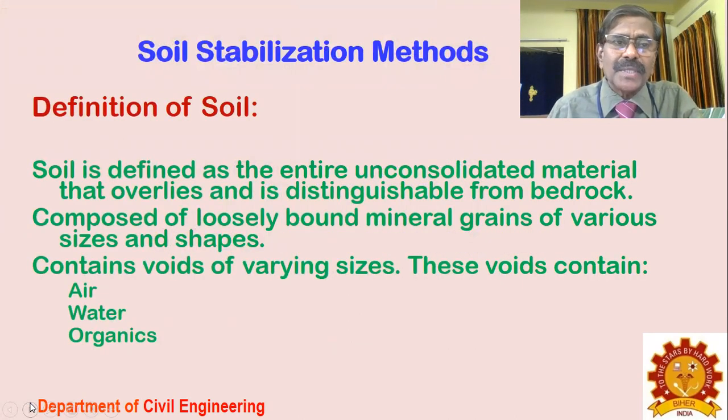If you want to define the soil, it is defined as the entire unconsolidated material that overlies and is distinguished from the bedrock. It's just a geological meaning. It is composed of loosely bounded mineral grains of various sizes and shapes, and contains voids of various sizes. These voids contain air, water, organics, things like that, as in soil mechanics.